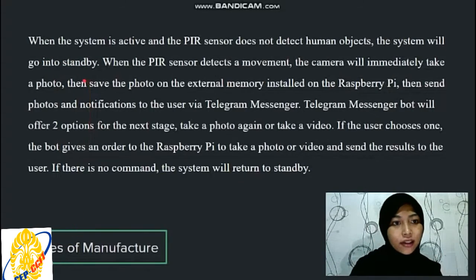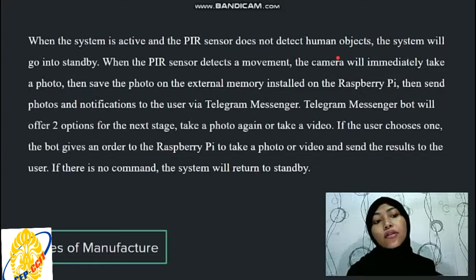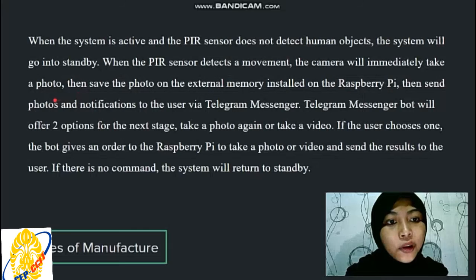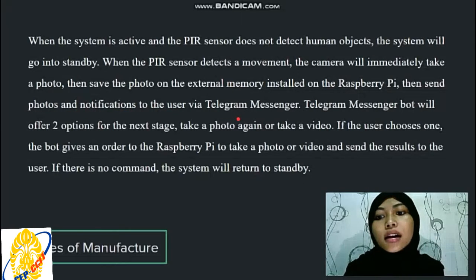Stages of manufacture. When the system is active and the PIR sensor does not detect human objects, the system will go into standby. When it detects a movement, the camera will immediately take a photo, then save the photo to external memory and send the photo and notification to the user via Telegram.